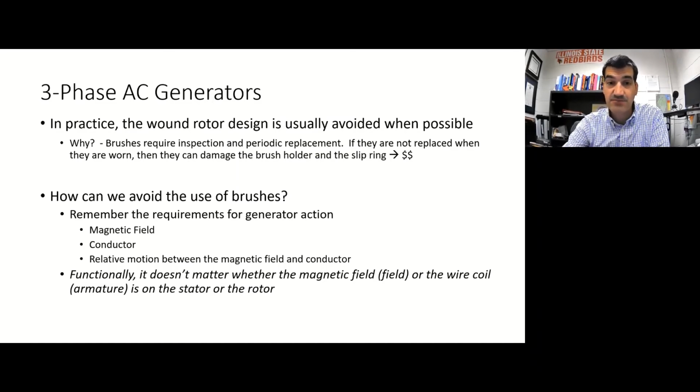You really need to get out and replace those brushes. And I'd be like, yeah, I know, we're going to get to it. But right now we're doing maintenance and I've got lots of other things. So we're going to get to it. Don't worry. We're not going to let the brushes wear down completely. But anyway, it's a big deal. You have to keep tabs on the wear of those brushes and you have to replace them before they wear down completely. All right, so we can get away from that.